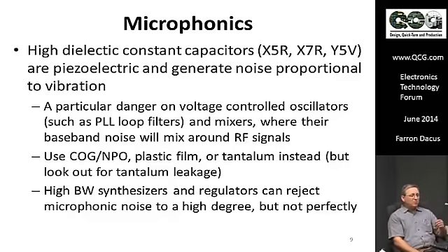I'll talk a little bit about some noise issues later, but the reason noise is so important in RF basically comes down to dynamic range. You take a 1-watt transmitter and you try and get some range out of it down to, say, a receiver sensitivity level, which for low data rates might be minus 120 dBm. That is a 150 dB dynamic range.